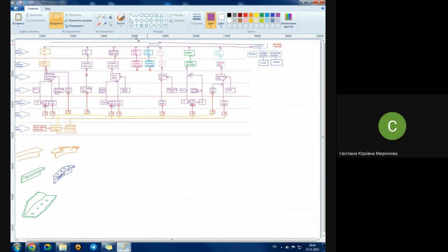Something like this. But once again, pay attention that you show the assembly jig in the line of size transferring to the frame. And why do we place it aside, contrary to the normal way in a diagram of assembling, when the jig is immediately in the chain? In order to show also the coordination of the jig. That is why it looks like this.